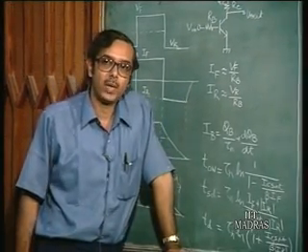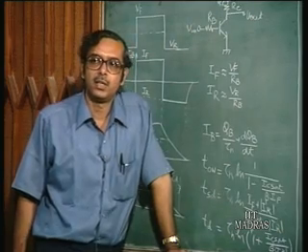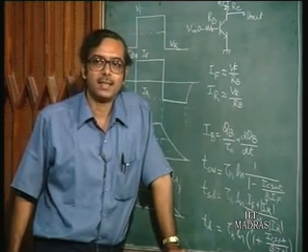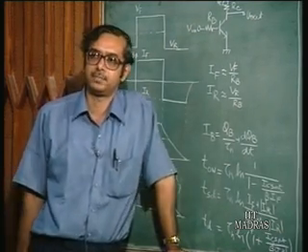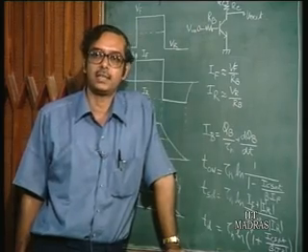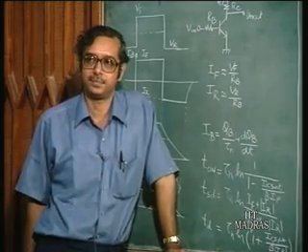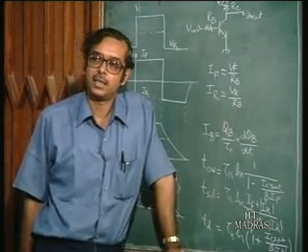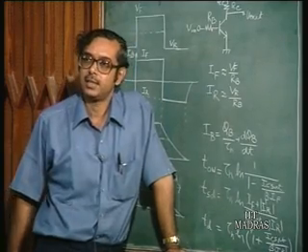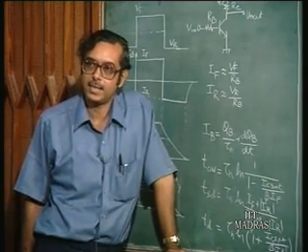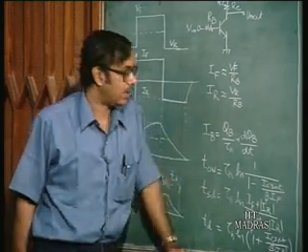The way to do it is to see that the transistor does not go to saturation. If the transistor does not go to saturation, then the stored charge delay is eliminated, isn't it? Now, how to do that?